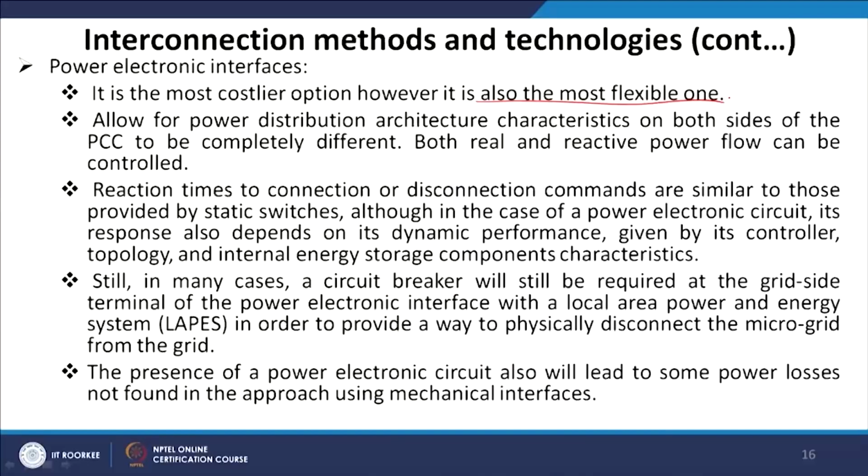It allows the power distribution architecture characteristics on both sides of this PCC to be completely different. You can have a different frequency, a different voltage level, everything can be different. Both real and reactive power flow can be controlled, that is the PQ control, and generally the power entry is through the active power filter or rectifier.